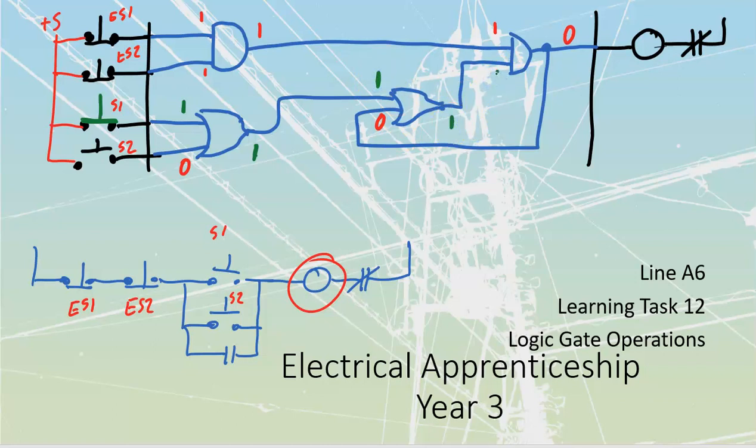And over here now we have got two highs into an AND gate, which means that my output goes high. This is going to go and energize my coil over here. And I'm also going to have this high get fed back up and into here. Okay, I'm going to take my finger back off this button because it's a stop-start station, right?